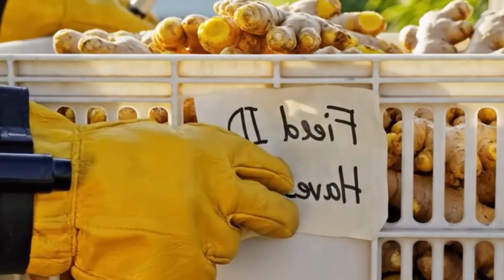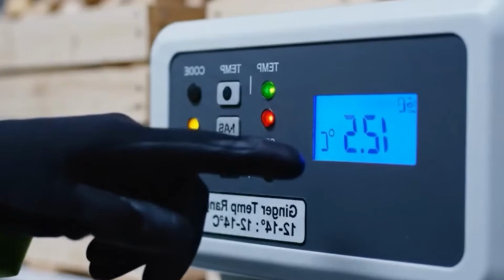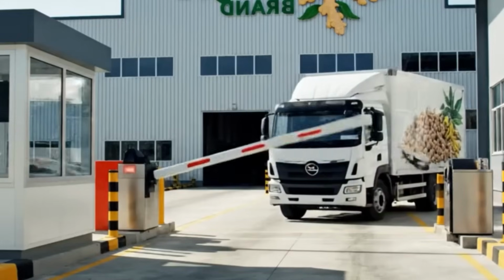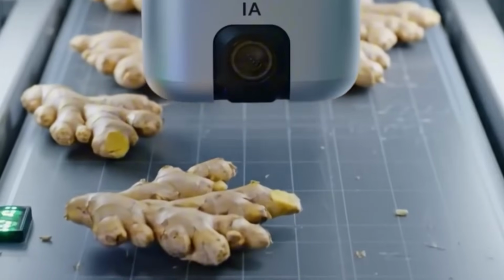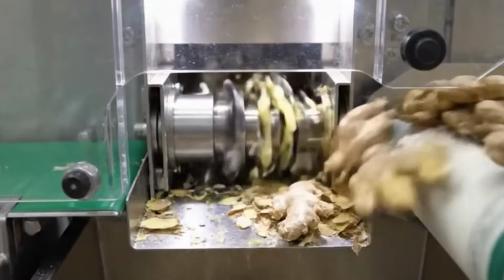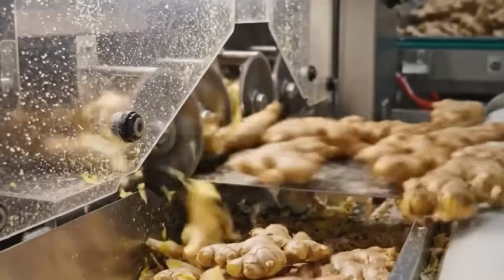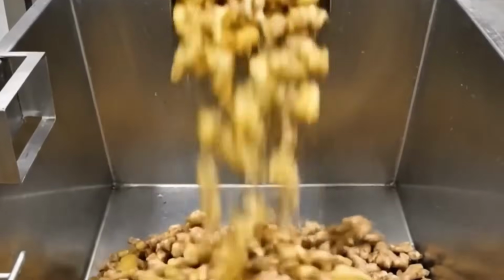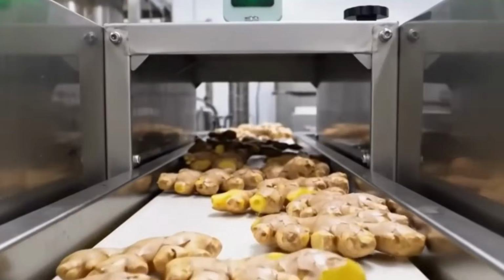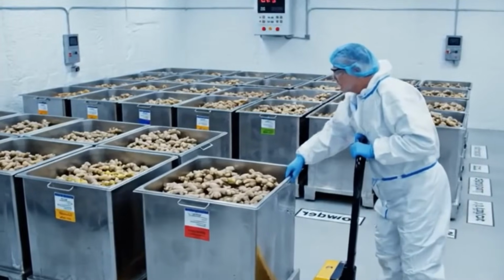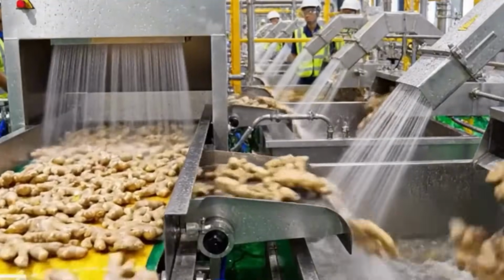Capping occurs immediately after filling. For bottles, closures are delivered by an oriented cap feeder using centrifugal force. Caps are guided into a chute and pressed onto bottles by servo-controlled capping heads with adjustable torque settings. For cans, aluminum ends are fed into place from a lid magazine. A seamer head performs a double-fold operation, curling the lid's flange over the rim of the can and compressing the metal layers together to form an airtight seal. Sensors verify each seal, and containers with improper application are ejected from the line.